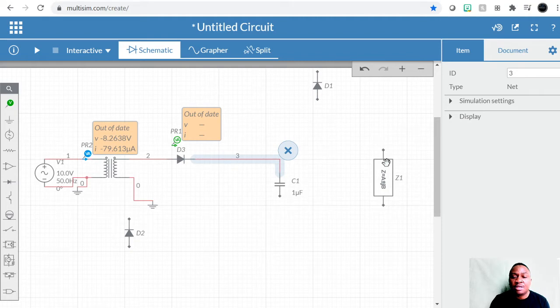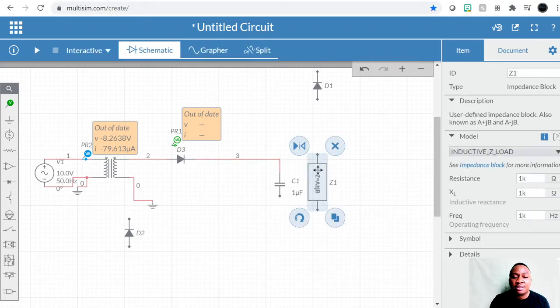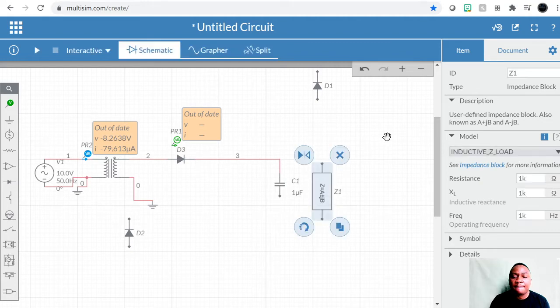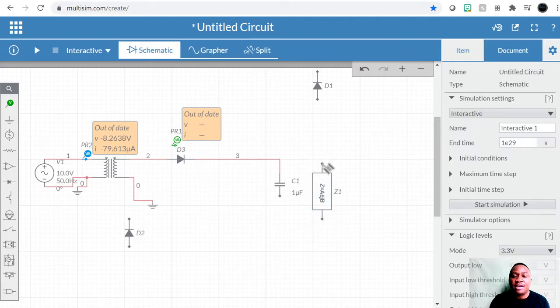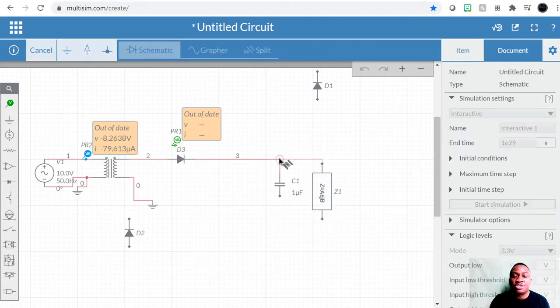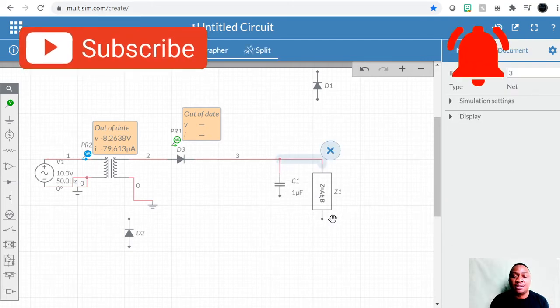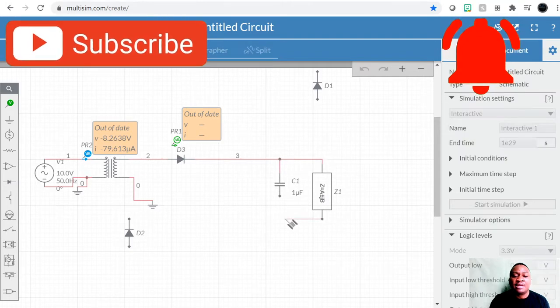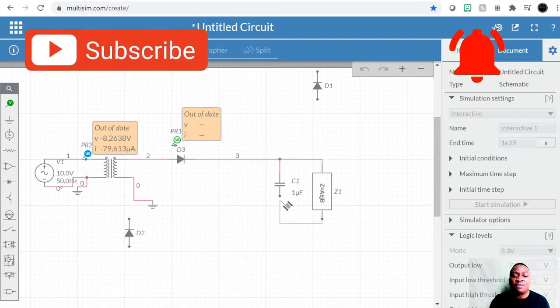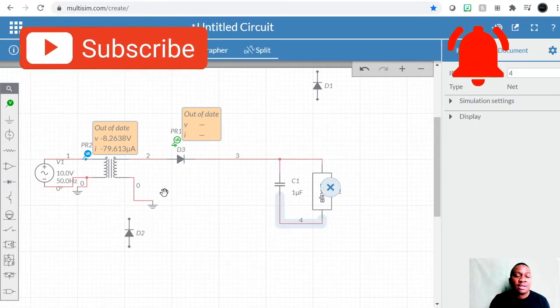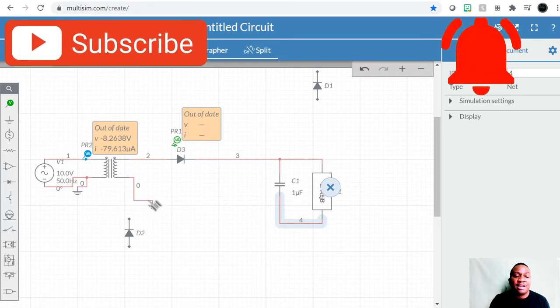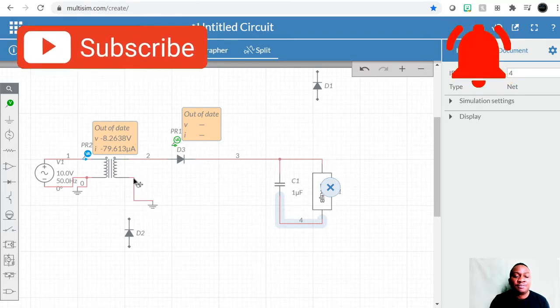And I'm gonna bring back this guy here. When you're rectifying the voltage source, make sure that the voltage of your capacitor is at least 4/3 multiplied by the value of your output voltage.